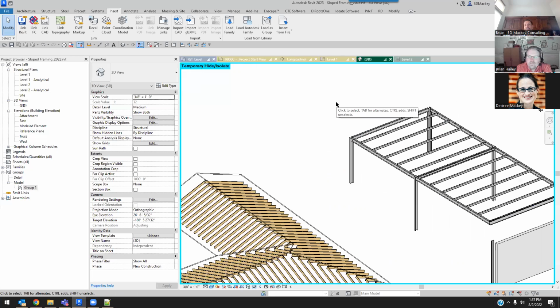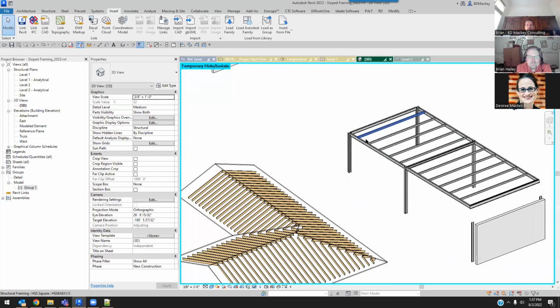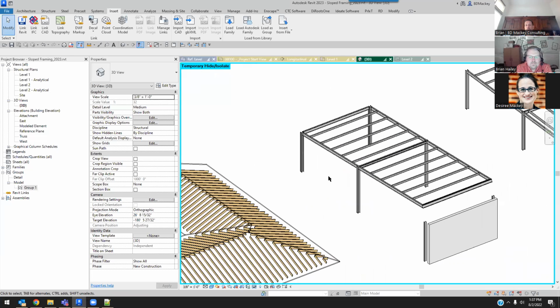I mean, groups are very, very finicky anyway. To start with any project, you have to set up all your content specifically to work with groups on the architecture side. Nothing can be face-based, nothing should be hosted, all these different rules. Can't really do stairs. You can do stairs, but not railings and groups, etc. Types of scenarios and things like that.